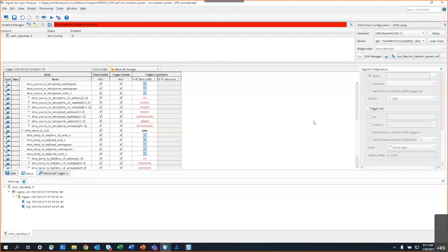I do know that sometimes if you have multiple JTAG tools open, like SignalTap and another on-chip debugging tool, or using System Console and Platform Designer at the same time, the JTAG starts having issues.